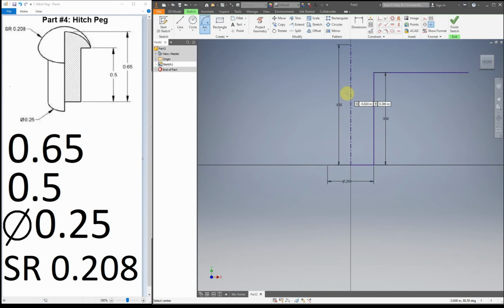And because we want it to kind of move around freely while we're putting the dimensions in, you don't want to have that. So I'm going to click on here. And sometimes you can get it to latch on right there if you click. Sometimes I have an issue with that, so I just like to extend it so they overlap, and then use the trim tool, trim them both up.